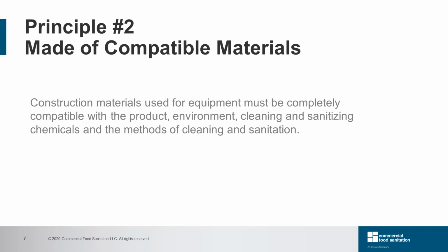Principle number 2. Made of compatible materials. Construction materials used for equipment must be completely compatible with the product, environment, cleaning and sanitizing/disinfecting chemicals, and the methods of cleaning and sanitation/disinfection.